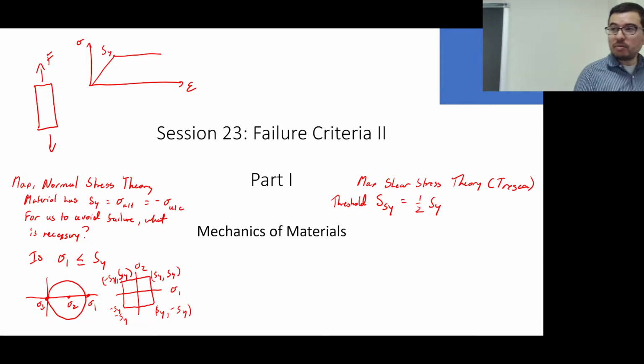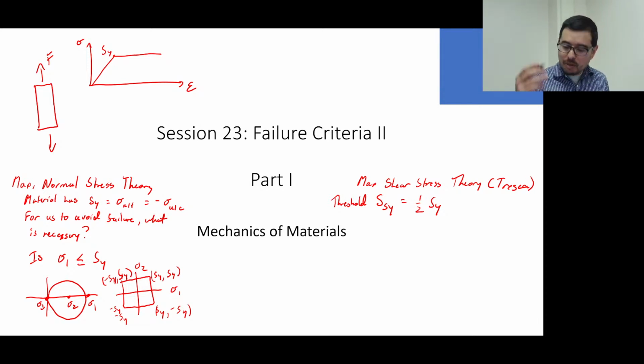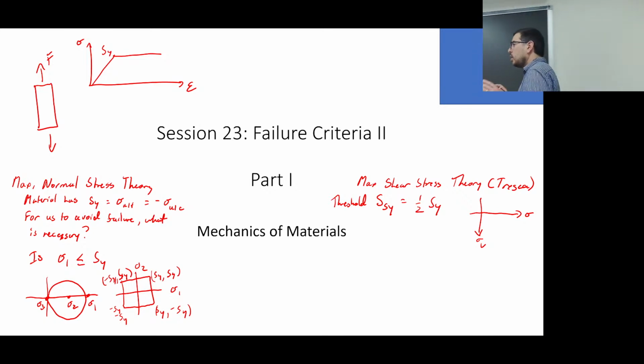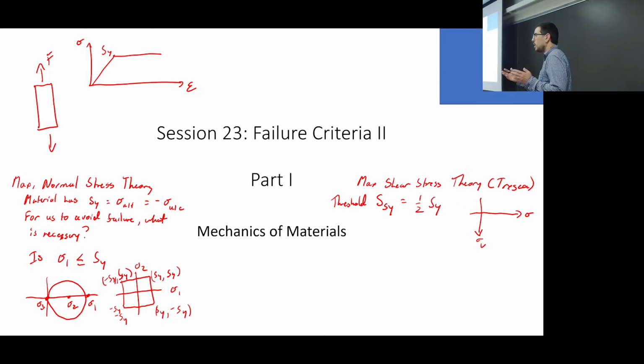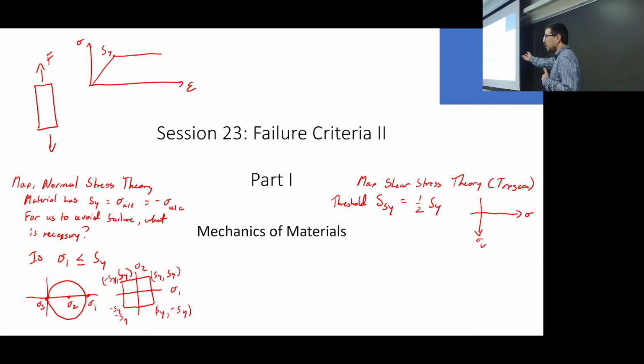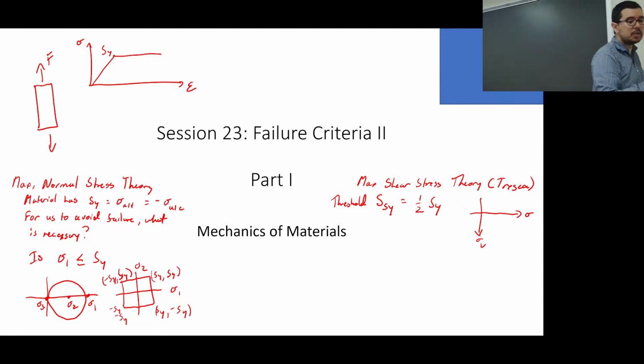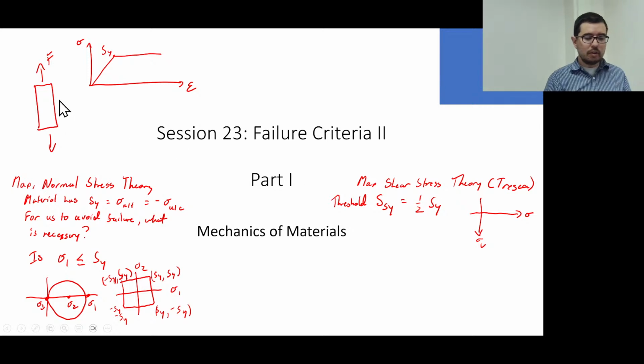Yeah, right. So you remember it from a video, or your head, right? It's from Mohr's circle. Why? Because what happened in Mohr's circle? And this is the threshold that we get from which test? From the tensile test, right? The uniaxial loading. When you've designed your structure, you don't necessarily think that your structure is going to have uniaxial loading, right? But this is a threshold that we get from the tensile test that we did over here.